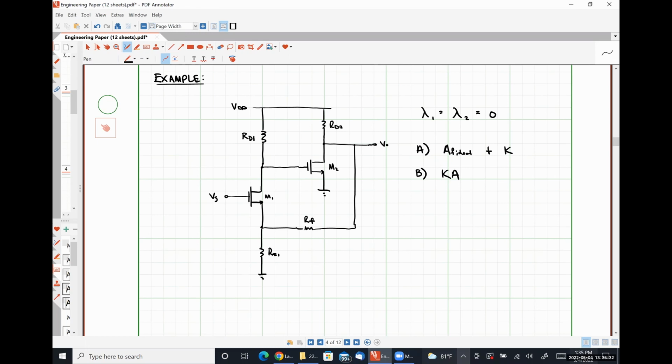So let's quantify a few things here. Okay. Let's start with what VI in this case is. Okay. So what does a transistor amplifier do? What's its purpose? It converts, in this case with MOSFETs, some small signal voltage, VGS, into a small signal drain current, ID, right?